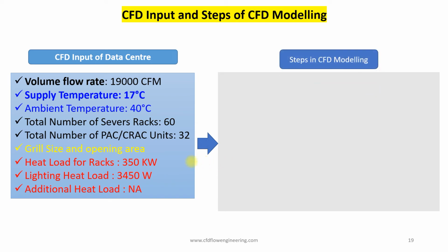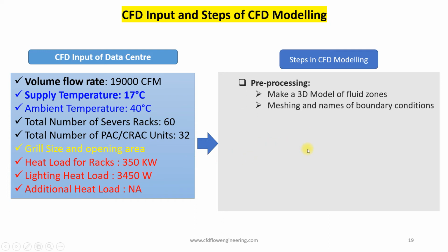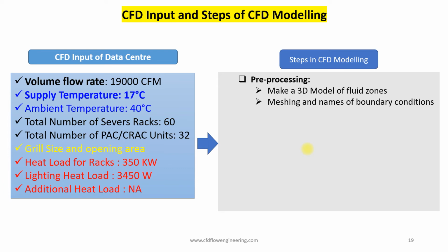What are the steps in CFD modeling? First is pre-processing. We have to make a 3D model of the fluid zone. Then you have to mesh and give names to the boundary conditions. Then simulation in the CFD solver.